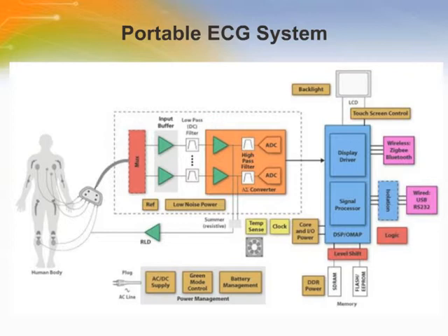The signal amplitude is generally around 1 to 2 millivolts peak to peak, with measurement difficulties coming in due to the presence of large DC offsets from the electrode to skin interface and 50 to 60 Hz noise interference from power supplies, RF interference, or even pacemakers, for example.